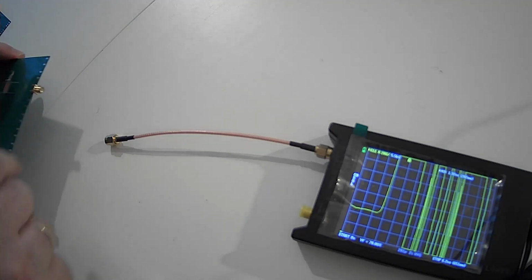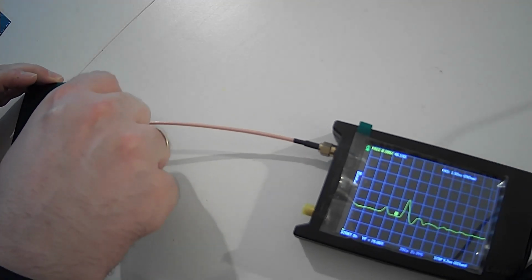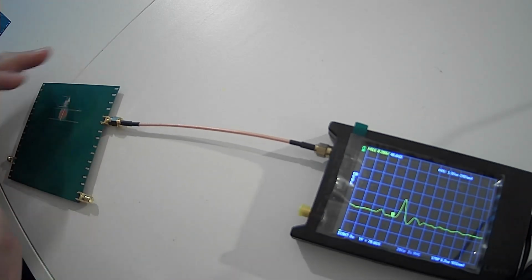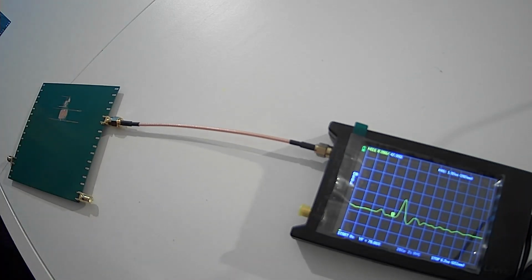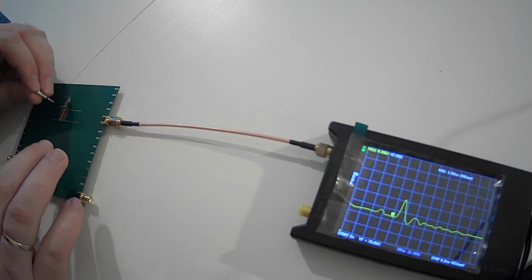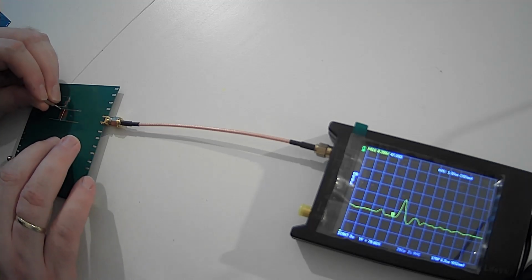And now let's connect it back to the nano VNA, because now I can show a cool thing. So probably you have heard that the signal on the return plane travels underneath the trace, and I now have a drill bit and can reconnect the ground plane. So let's first do it on the side of the trace.